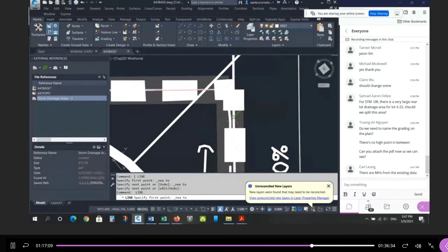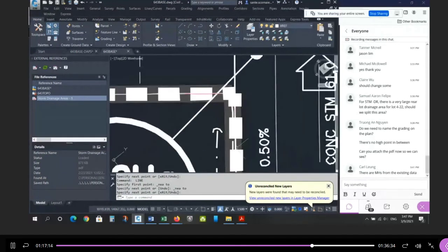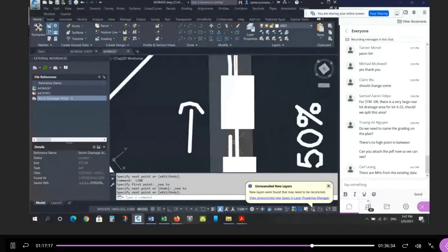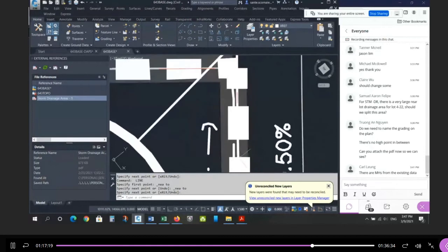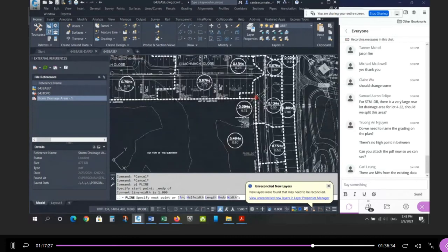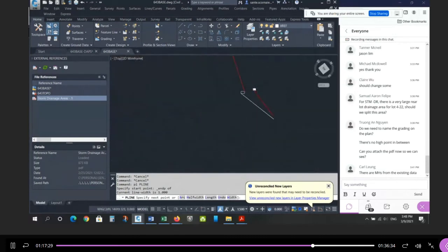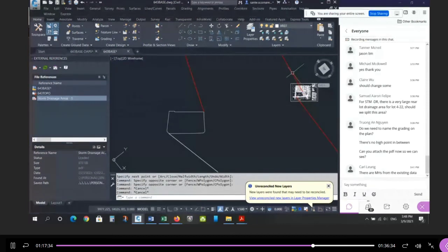And then you also want from here to here, the outside. There's always a double line right here. The reason there's a double line is because there's a legal boundary. There's an extra foot that's identified so that nobody can cross into the property. So from here to here, that's the corner. So I'm going to draw a polyline from this corner, and that point represents this blue dot. This blue dot belongs here, and this blue dot belongs here.